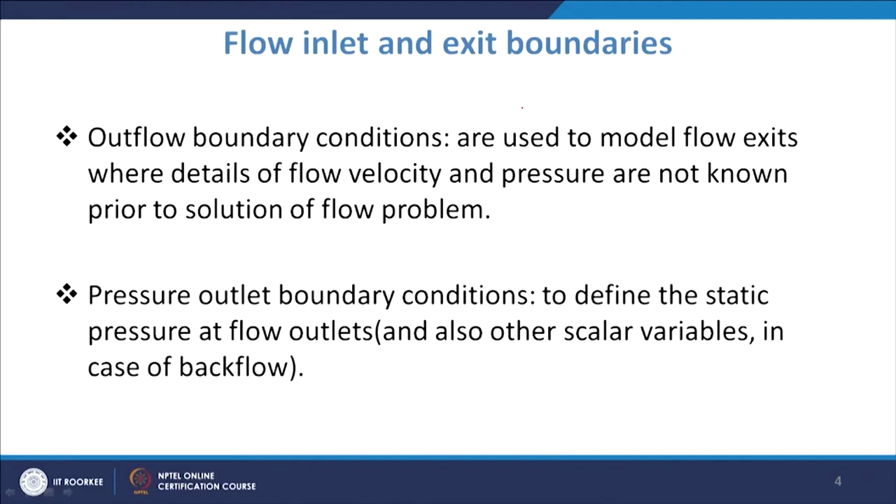Apart from that, we should also know that at the outlet you sometimes have the pressure outlet boundary condition, which defines the static pressure at the flow outlets. So, these are the two kinds of boundary conditions applied at the outlet.